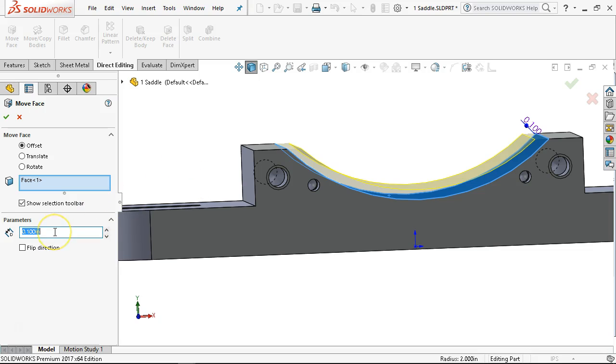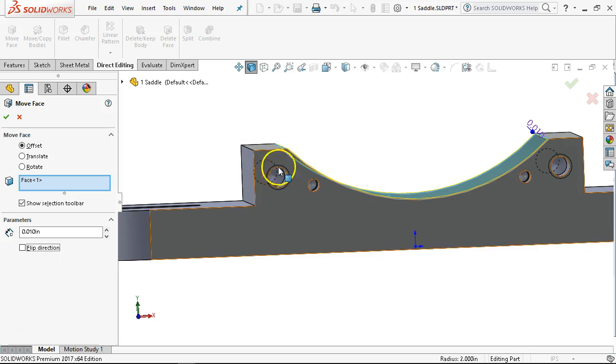All right, so 100 thousandths, no, maybe 10 thousandths for grind. Right? And then this wheel is going to have to be set at the diameter and move back and forth, or we're going to need a really big wheel and have that surface so that it can move back and forth as we go down. All right, so what is our grind process even going to look like at that point?